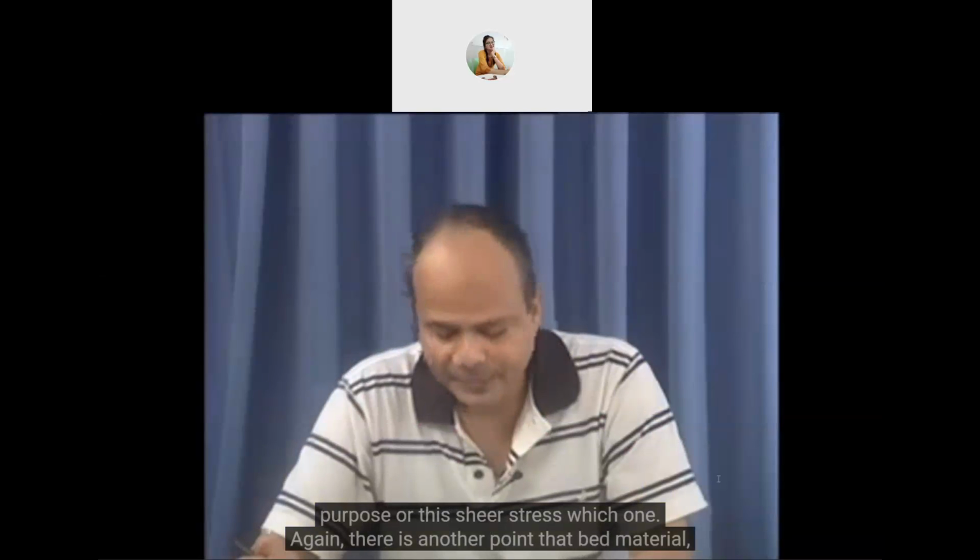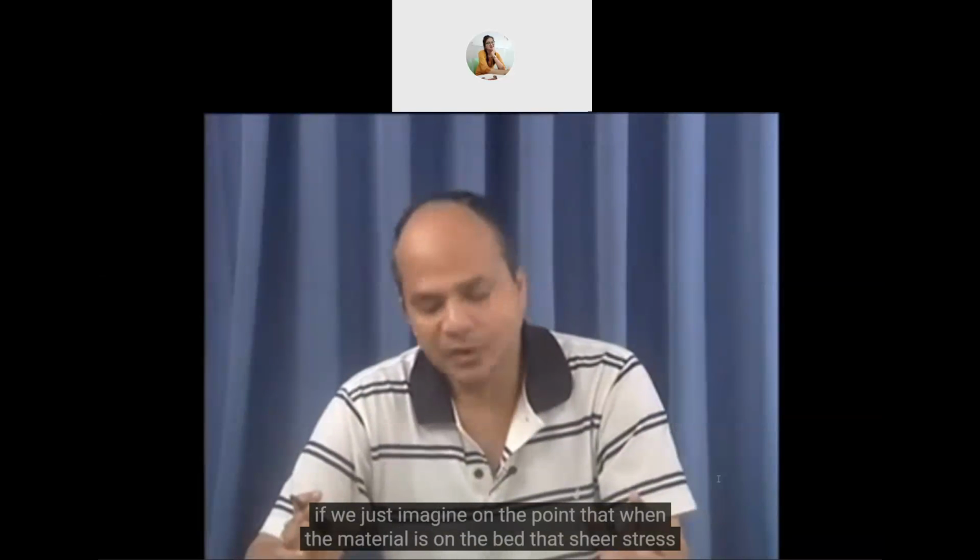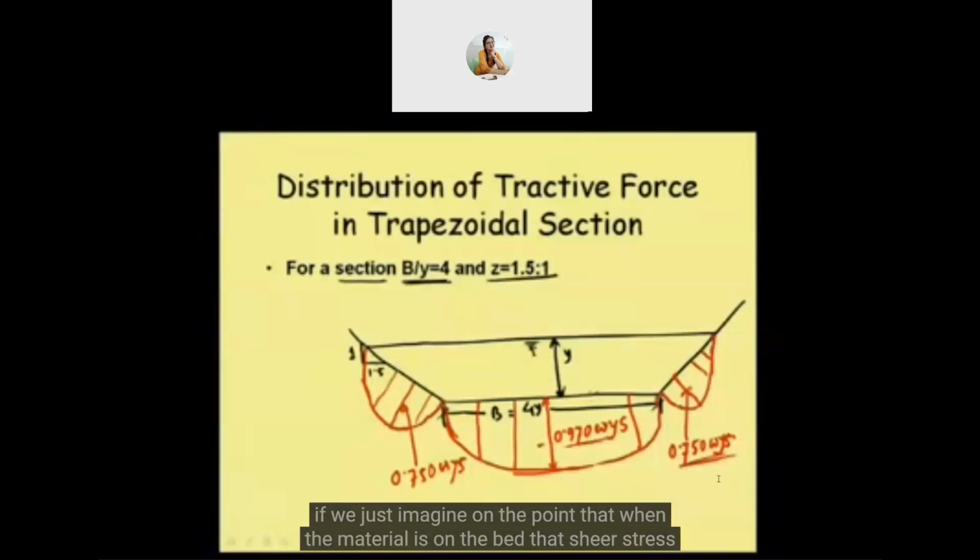That bed material, if we just imagine the point where the material is on the bed, the shear stress required to move this particle will be more than the shear stress required to move this particle from this particular point, because this is at rest, and it has its weight, say submerged weight, and some friction, so the force must be sufficient to move this particle by overcoming those forces.